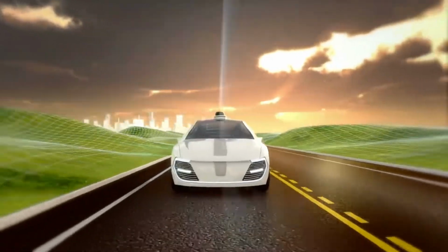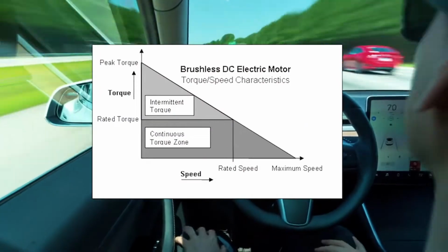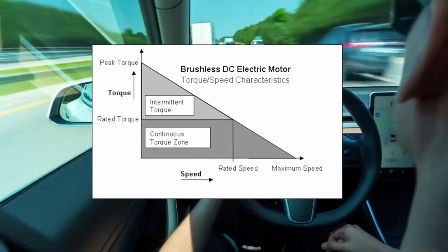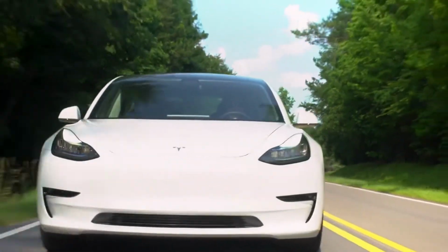The power produced by the electric motor is transferred to the wheels by a gearbox. In most electric cars, such as Tesla's, Volvo C40, Audi Q4 e-tron, etc., a simple single-speed transmission is used because the electric motors are efficient in a wide range of operating conditions. A single-speed gearbox gives these cars really good instant acceleration with no delay.